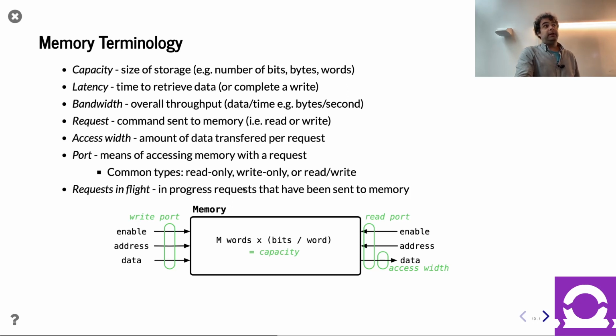For SRAM, in practice, 2 ports on an ASIC is not unreasonable, it's common even. 3 can be done. For a single SRAM array, going higher than 3 is doable but rare.